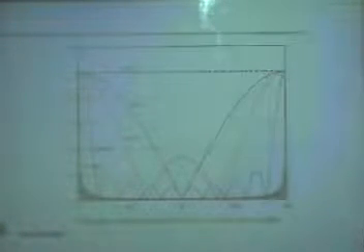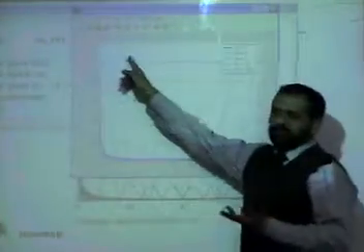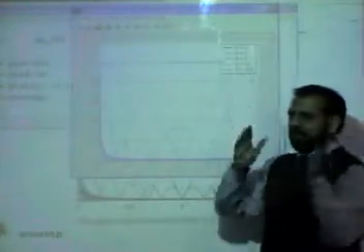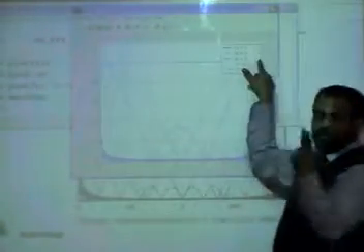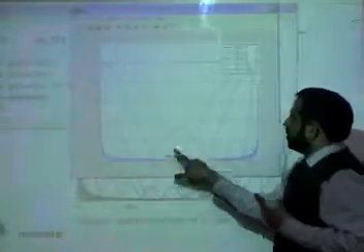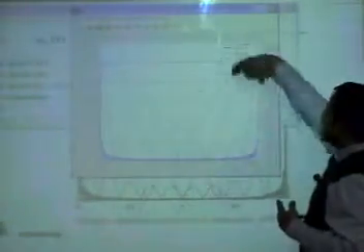Moving average. If you look at the code, the first case does nothing. It just takes a moving average filter of length one, with one coefficient only. One coefficient means you are not doing anything. Input is the same as the output, so there is no change in the frequency content. Then a moving average filter with 2 coefficients, with 3 coefficients, and similarly it plots all of them. It's a good MATLAB code. You can learn a lot from all the examples given here.